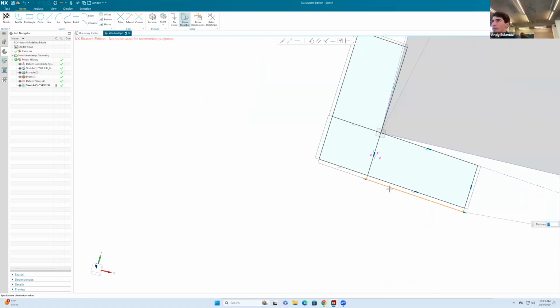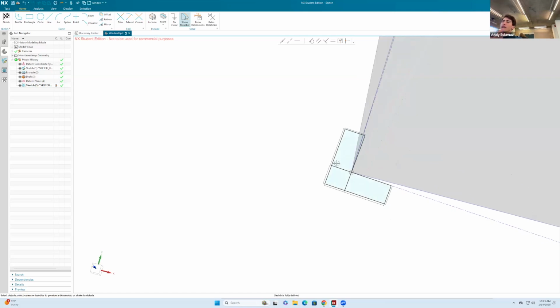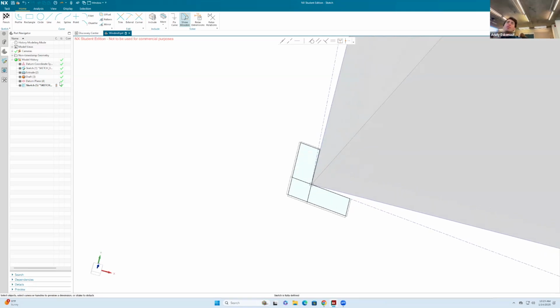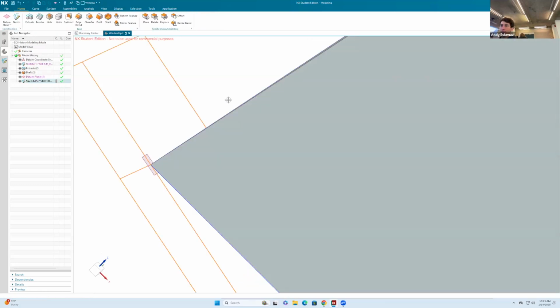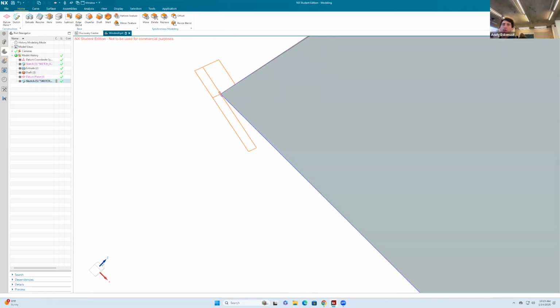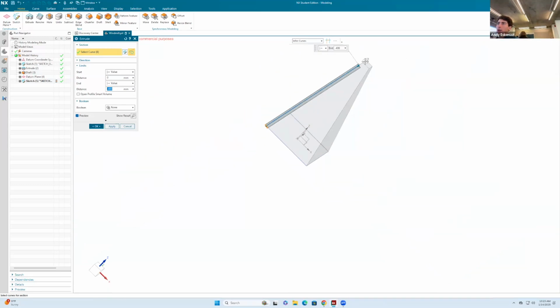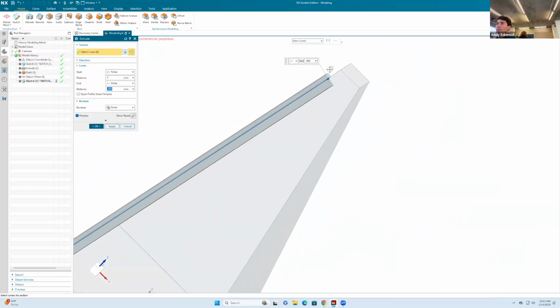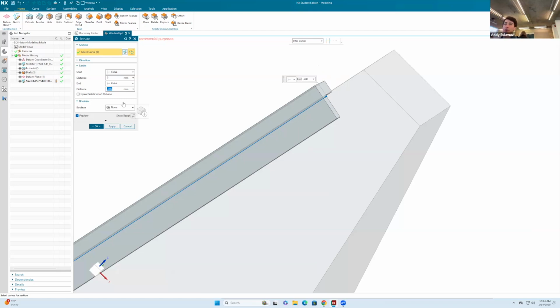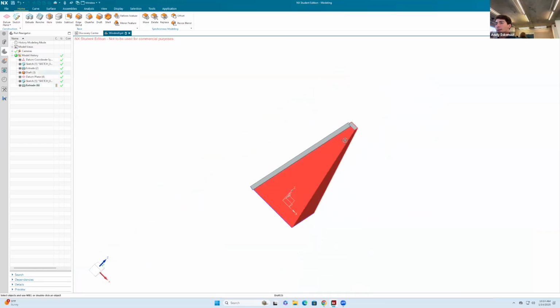I promise I will go around to help you guys. But it is just to get an L shape. It doesn't matter too much the dimensions. But the point now is that if I click on finish and I have this structure in there, then I can go to extrude. I'm gonna change the direction to make it -400. And you see how our L shape is being extruded in this direction. In fact, I'll be quite loose. There, I'll make it negative 420. And just make sure that you have the none in there.